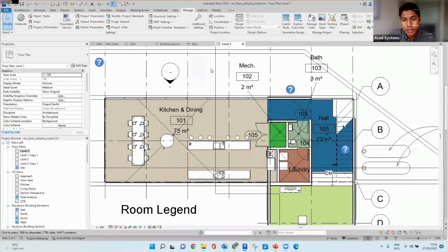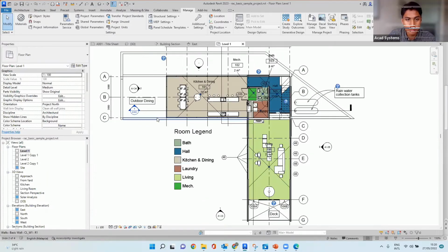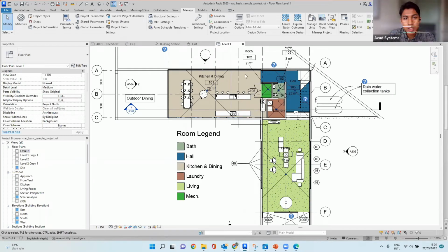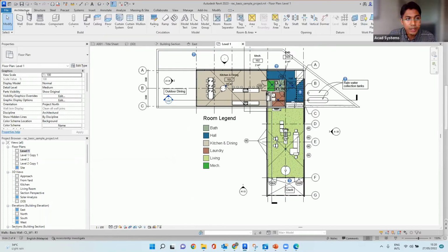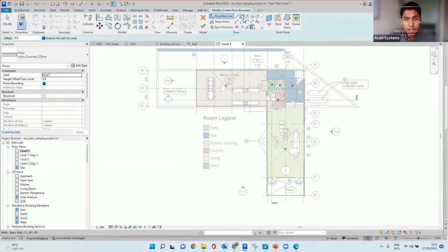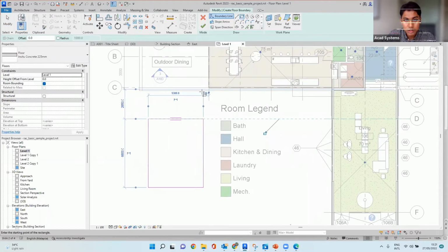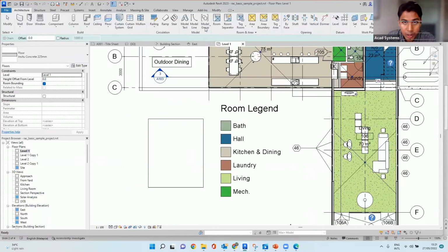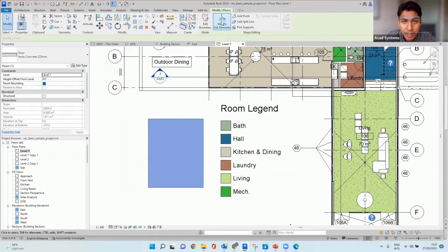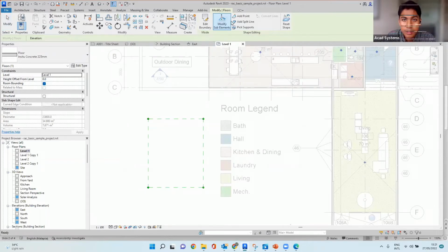And next, we will be looking at a floor edit. On a floor edit, I will be creating one floor. So we go to the Architecture tab and then Floor. Just draw a sample floor here, and then I click on OK. And then I click on modify sub-elements. I add a point, I place it here, for example.